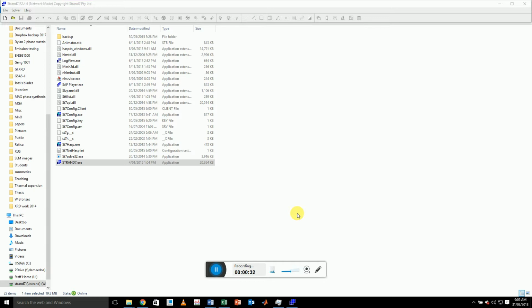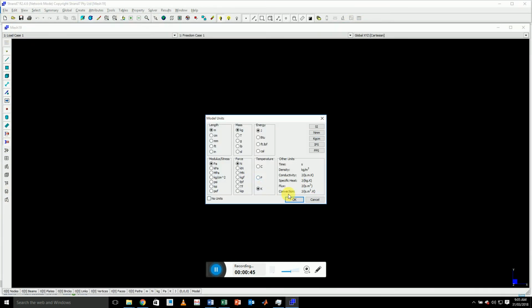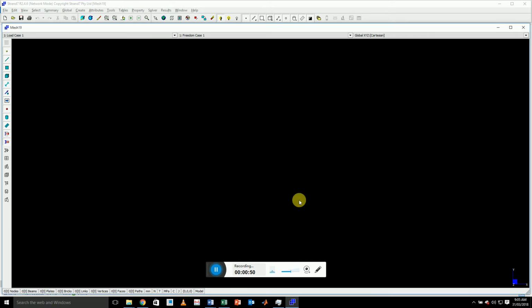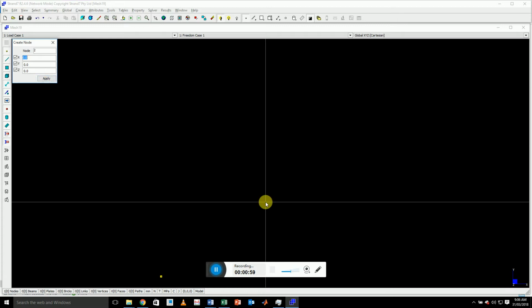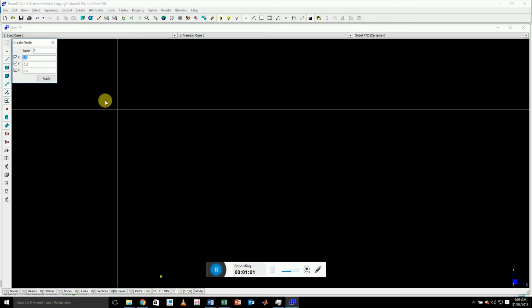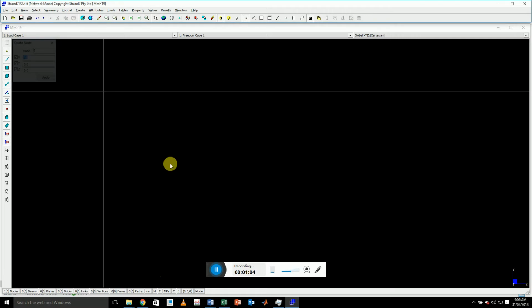So what I want you to do is go through this video with me, pause it every time I press a button, and build the truss along with me to get you some practice. Alright, that's the point. So I've just opened Strand. I'm going to go new. I'm going to work in newtons and millimeters because I find it more convenient. You don't have to. I'm going to start by creating a node at the center of my blank universe, 0, 0, 0. Just a reminder, I am building the truss that you built as your practical competency in this task.